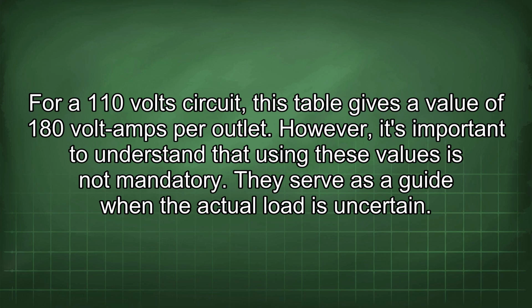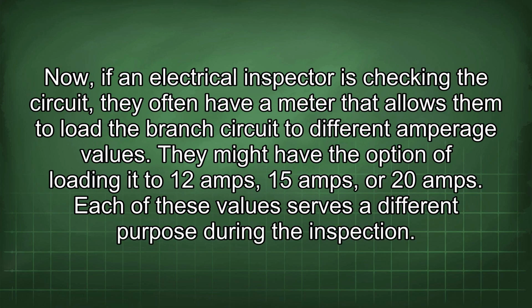However, it's important to understand that using these values is not mandatory. They serve as a guide when the actual load is uncertain. Now, if an electrical inspector is checking the circuit, they often have a meter that allows them to load the branch circuit to different amperage values. They might have the option of loading it to 12 amps, 15 amps, or 20 amps. Each of these values serves a different purpose during the inspection.